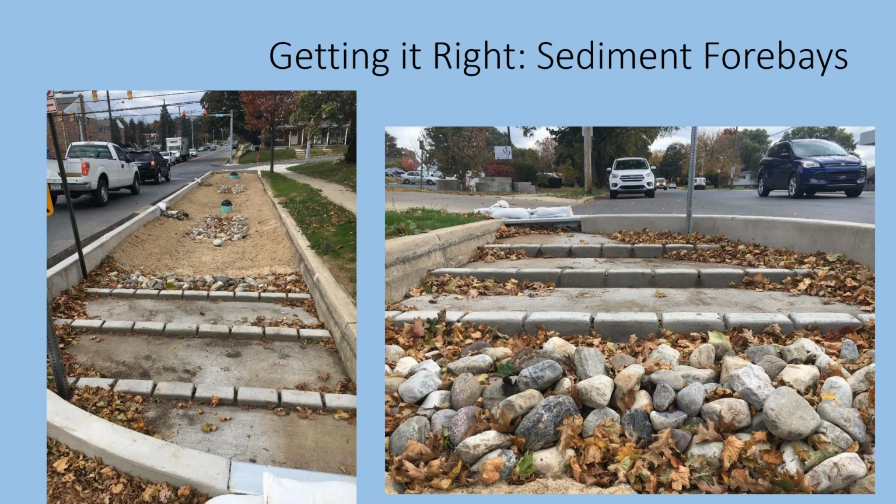We approached them with our concerns and walked through our retrofits with them, and this has now become one of our standards. And you can see it's pretty much the same. We've got a nice flat concrete pad for our maintenance guys to go in with a flat edge shovel, as well as the velocity dissipators and some fall in between those velocity dissipator rows. Next slide.